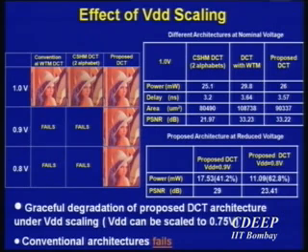So if I look at a 1 volt DCT, the first one in that column shows the conventional DCT with a Wallace tree multiplier. This one is a conventional DCT with a shared multiplier that we developed. And this one shows the proposed DCT. The interesting thing to note is that for 1 volt, everything certainly works very well. But when you scale your supply voltage down to about 0.9 volts, I'm not showing the images, they actually look pretty horrible. But these ones look reasonable. If I enlarge the image, you're going to see some grains right here. But what it really shows is that, down to about 0.8 volts or so, you get a reasonable quality image. So what does it mean in terms of power consumption? A 0.8 volt DCT would give you a power improvement of about 60% compared to the original one.